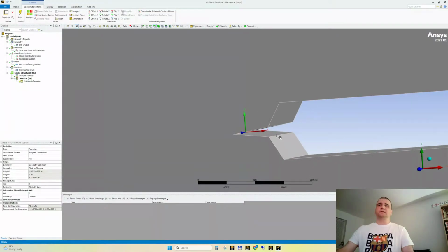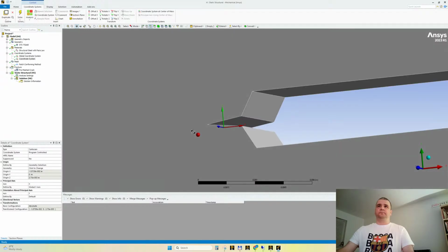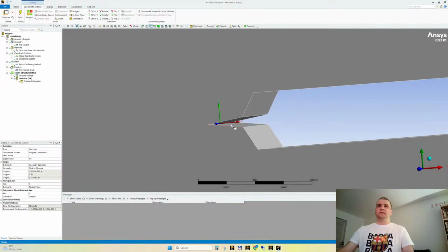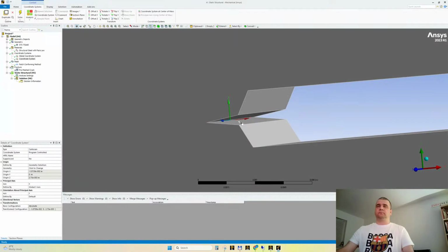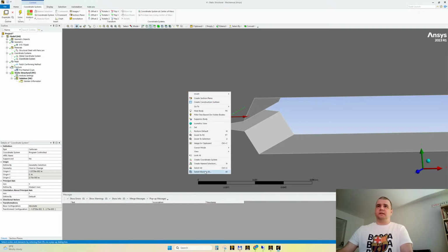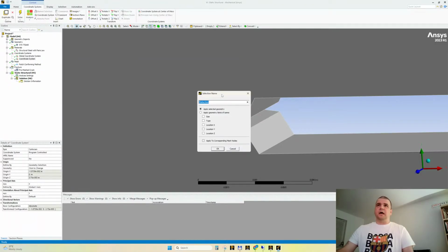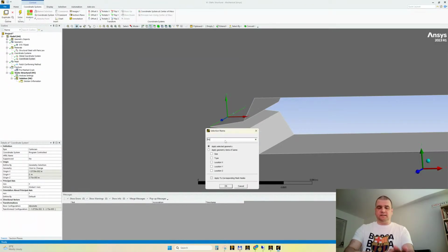How do we do this? Look here. So, select the edge. This is the edge. We need to create a named selection. We will not go with right-click, create named selection. Only what I'm doing is just pressing the letter N from the keyboard. It's so easy. So this is what I'm doing, N. I will give it a name. I said this is the front.